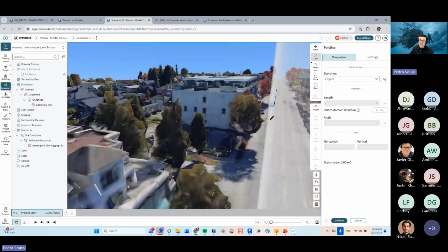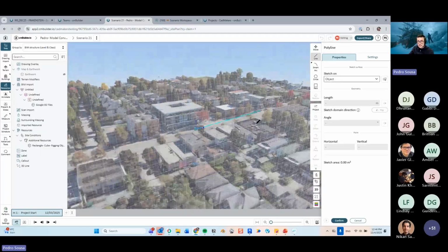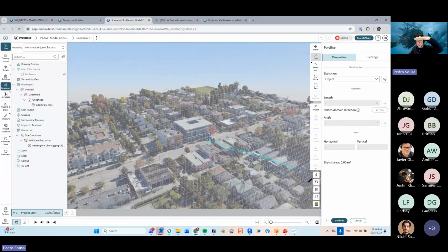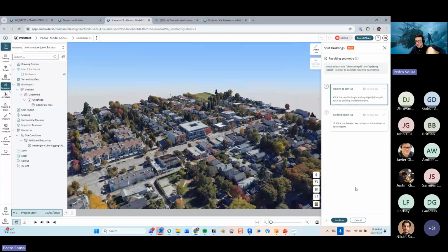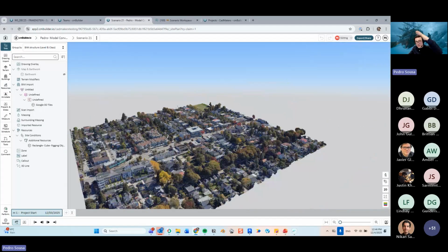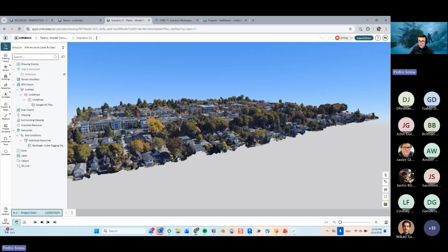So now that's a vertical face. Okay. So keep that in mind because, let's say they have a taller tower over here. You want to slice that up in several different levels, so you can do a demolition kind of simulation. So if you use a sketch that has an angle, your slicing elements will be completely wrong. Okay.